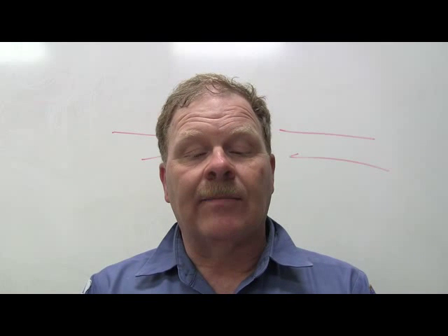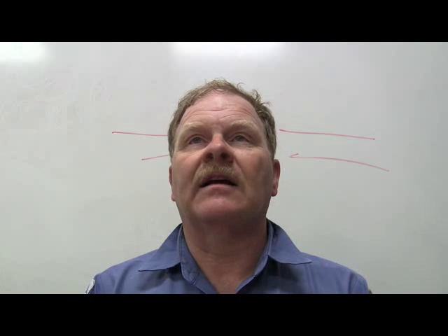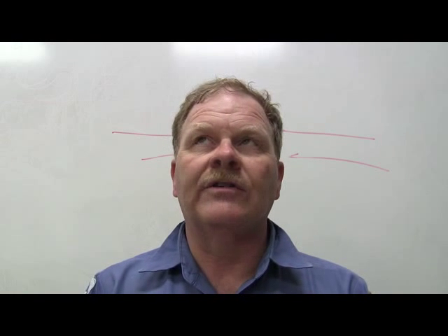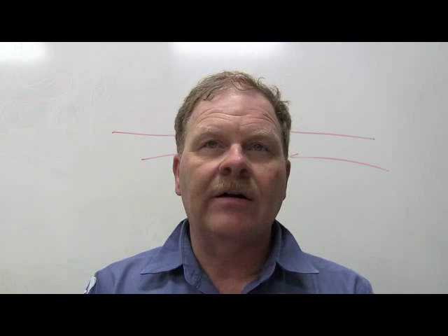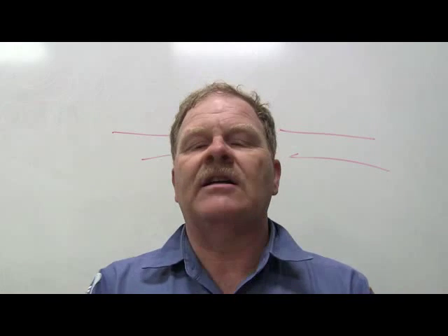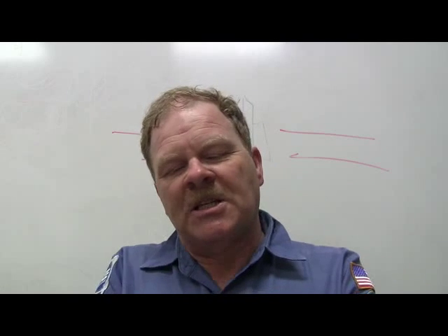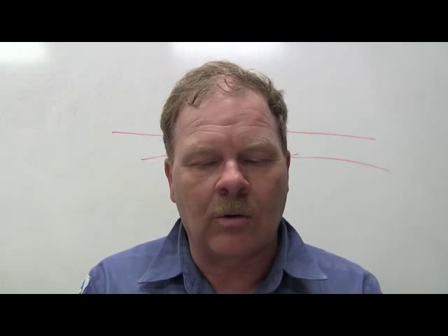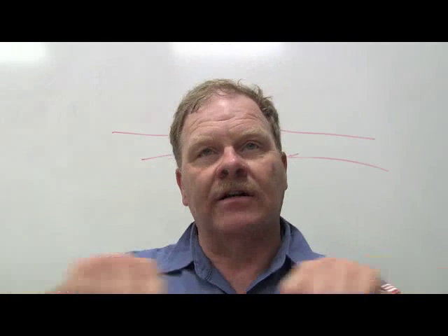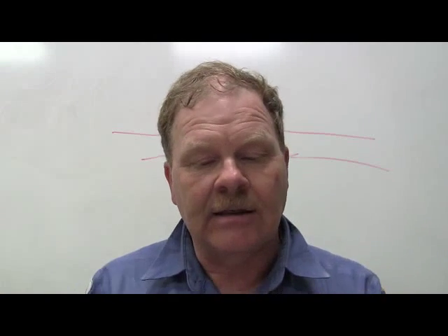See, I want to tell you something. With the flare fitting, sometimes, like if you're having to change the orifice tube on one of these Chevrolet trucks, be prepared to go ahead and sell them a condenser, because whenever you try to break them loose, most of the time they will not come loose. They're just all seized up, galled together. You can't get them apart, like they're welded. But I like the spring lock coupler lines, they can't do that.